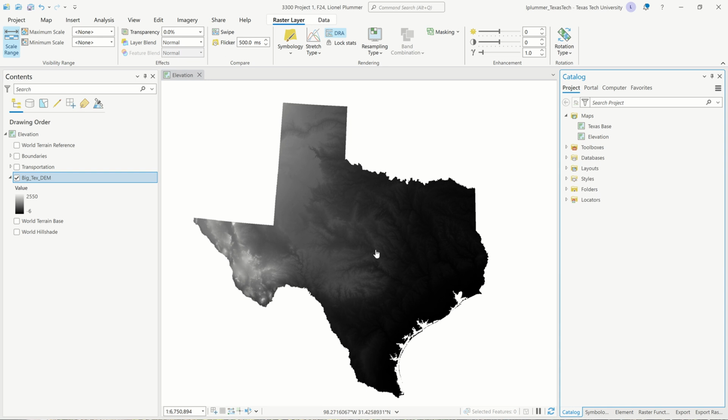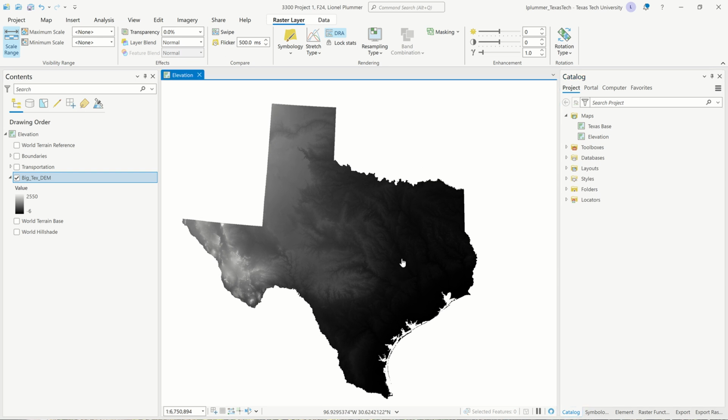Now, when I zoomed in, did you see just how detailed this data is? If we used that, we would run into a lot of problems because it's over detailed for contours. We like contours to be smooth flowing lines, and if we used it like this, it would really just be jaggedy. The file size would be too big. So what we're gonna do is blur this DEM.